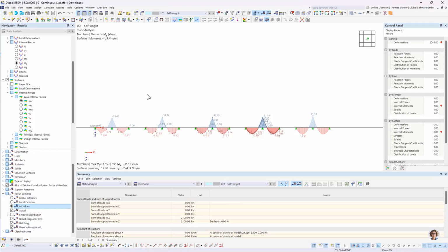But if you think about a 20-story building and you would go for a mesh which is as fine as this, or if you think about the dynamics field where we not only have the spatial dimension but also the time dimension, and we're gonna calculate these equations once each 0.01 seconds, we will increase our calculation time by quite a lot.